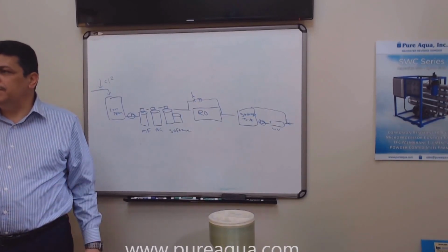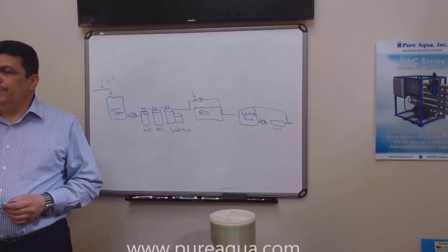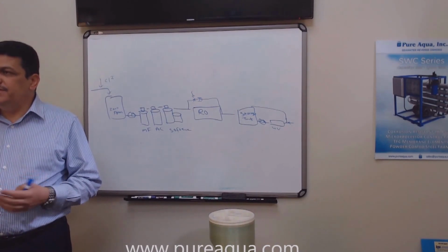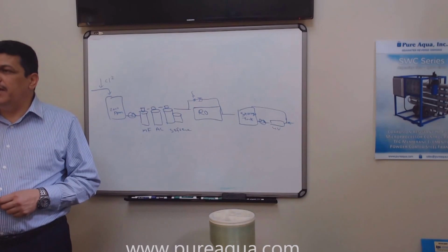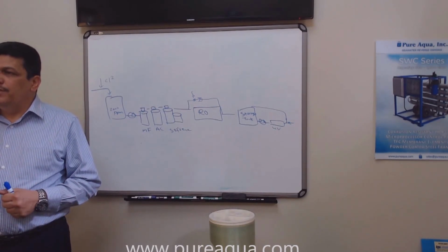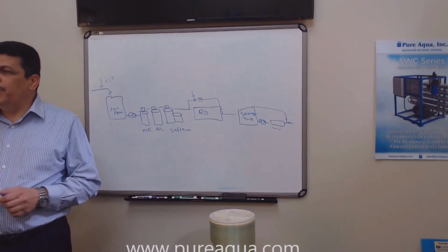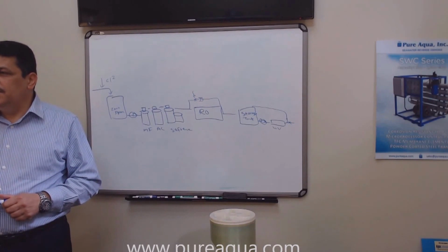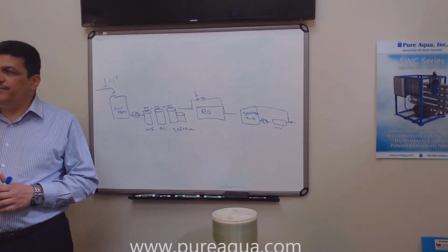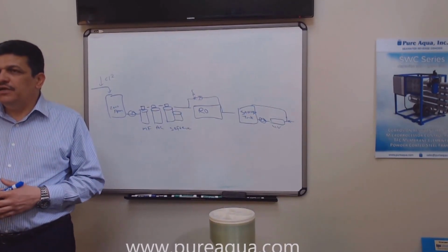Dissolved, you need an extra energy to force the water to go through the membranes, or the semi-permeable membrane, which is the reverse osmosis. So, again, like in the first session, we said that reverse osmosis is an expensive device that you want to utilize only for desalination or lowering the dissolved minerals in the water. So you don't want to use it for just conventional filtration. It's a bad engineering feature for that. It's expensive.